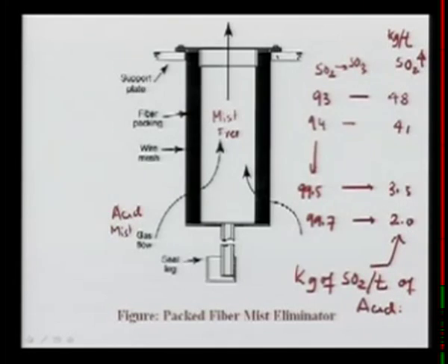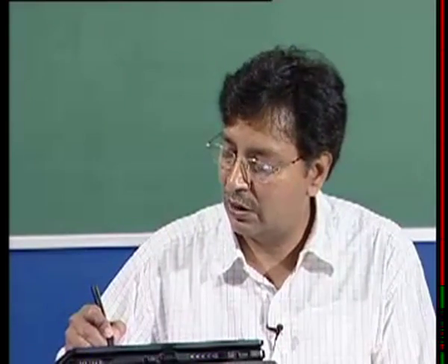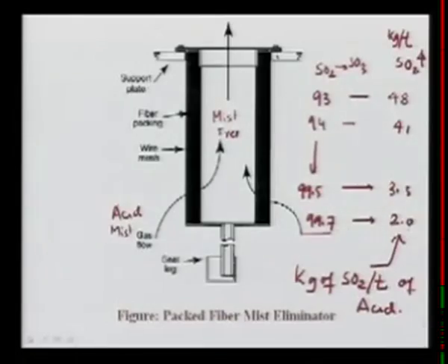Well, in summary, as I have been saying again and again, the conversion of SO2 to SO3 is a key process, and if we can handle that, then the SO2 emissions will significantly reduce. Just again I repeat, with very high conversion, the emission is very, very small. Similarly, the acid mist emission will depend on how smartly you are operating your absorbing tower.